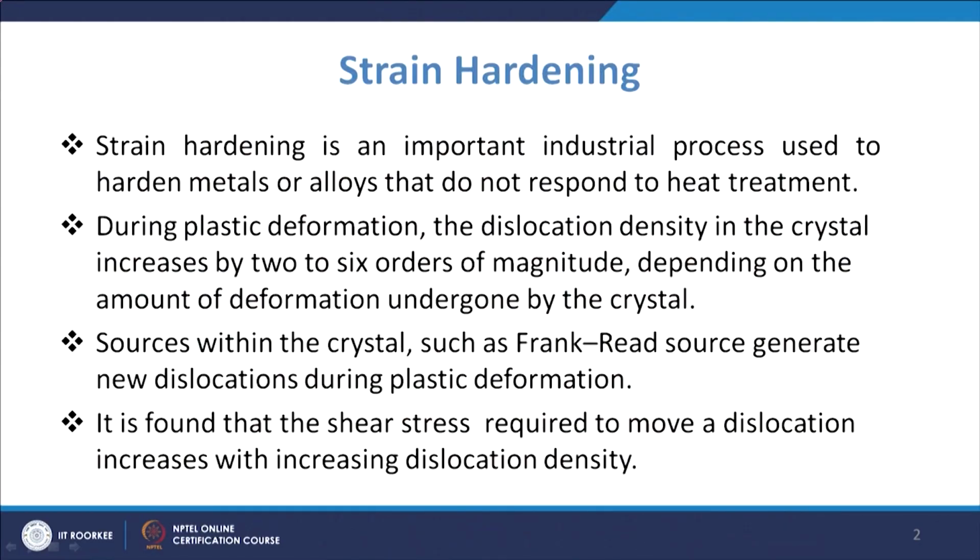Sources within the crystal, such as the Frank-Read source, generate new dislocations during the plastic deformation, and the shear stress required to move a dislocation increases with the increasing dislocation density.